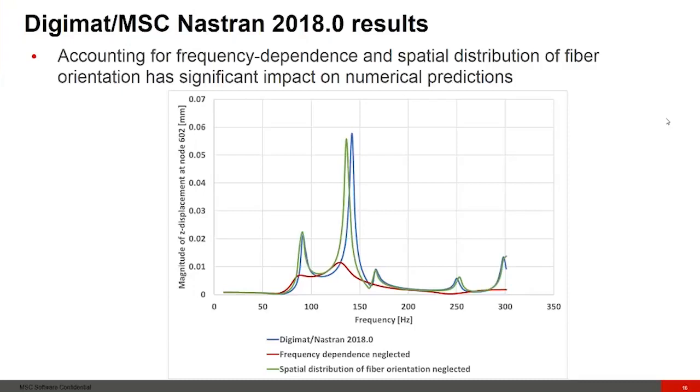We've also improved output for a complex eigenvalue analysis, in which case we correctly identify rotor whirl type for each rotor in the model for both synchronous and asynchronous analysis. We've included cross-coupling terms for an enhanced PBUSH2D entry, which can be used for bearing analysis and such. We've also added SEDAMP handling for correct modal damping in super elements. And finally, in this version of MSC Nastran, we support rotors in part super elements.